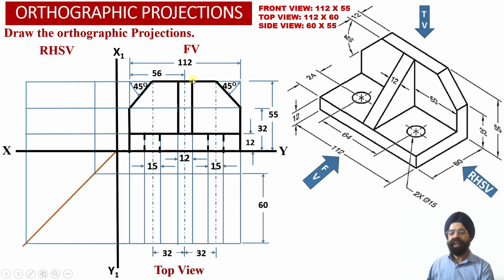So now here we have been able to obtain the apparent shape projections corresponding to this web which is lying perpendicular to the front face of the solid over here. So since this surface happens to be inclined with respect to the vertical plane, the projections of this rectangular surface onto the vertical plane will be projected as apparent shape projections into the front view projections over here.